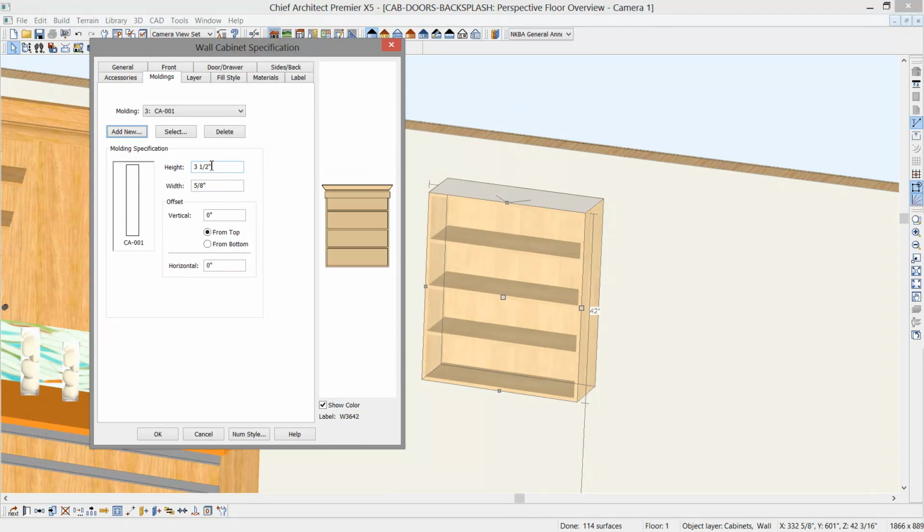And let's go ahead and set that to be something like 2 1/8 inch, 1 inch in width. The vertical offset here, minus 6 inches. Remember, that's an aggregate. And then the horizontal offset to be also 1/2 inch.